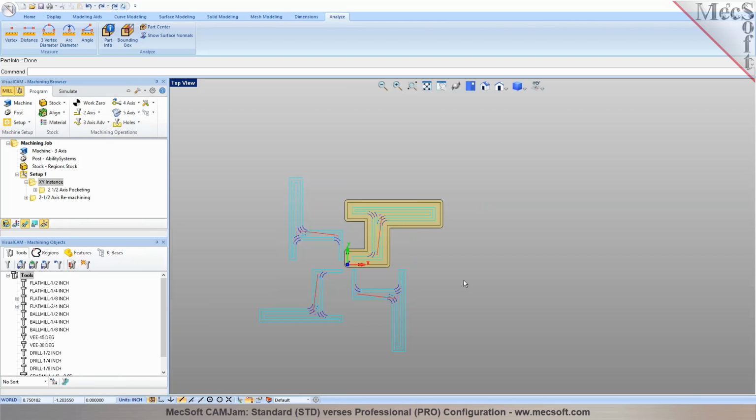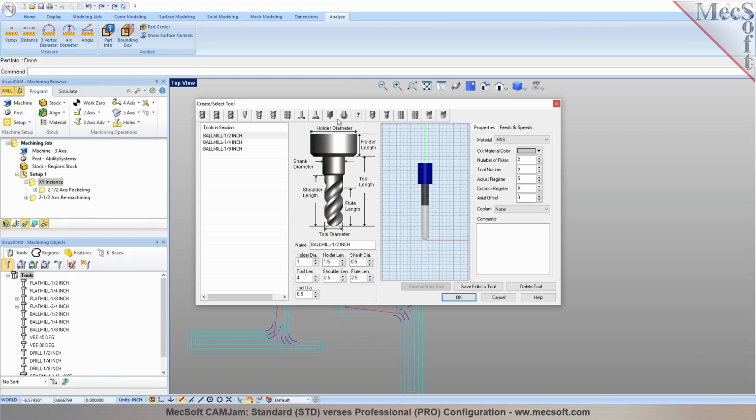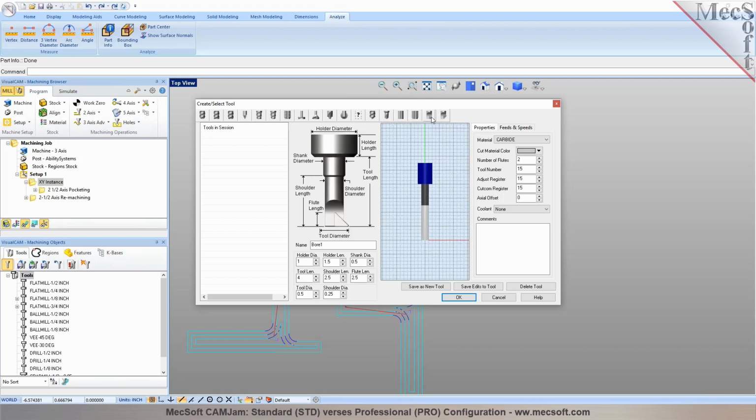Are you talking about the milling module, or the turning module? The mill module. Okay, so you were defining a tool like a grooving tool. Do you happen to know which of these tool types you chose for it? The bore operation is basically like a drilling operation. It uses the center of the geometry you pick to establish the centroid, and then it creates a drill operation. It's just going to drill at the center.